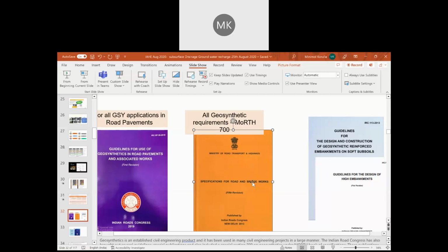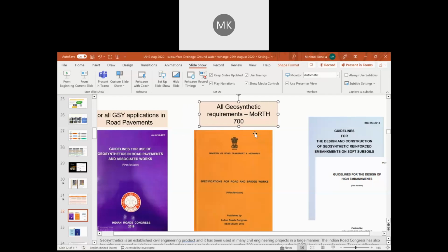Okay, I know that I can reduce the thickness, I can really bring down the material cost. But the client is telling me no, the material is already procured, we don't want to reduce the thickness but increase the durability. What I will do, I will go in a little luxurious way. I will introduce a base reinforcement and sub base reinforcement, which you are seeing as the dotted green line. Okay, and then an asphaltic reinforcement.